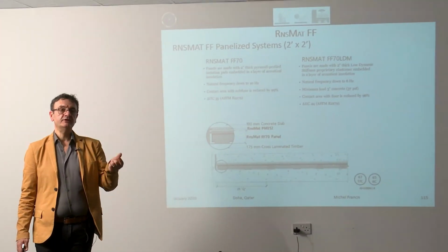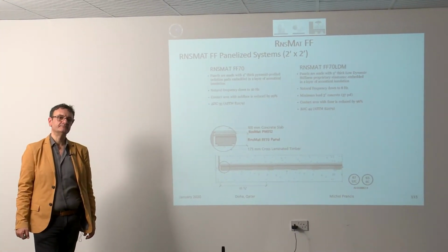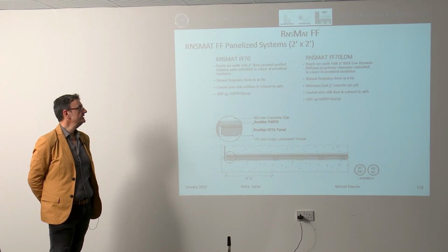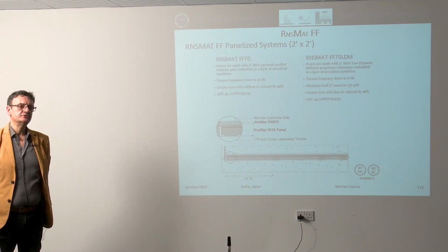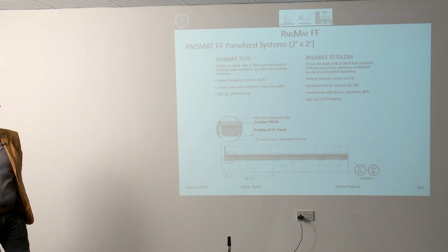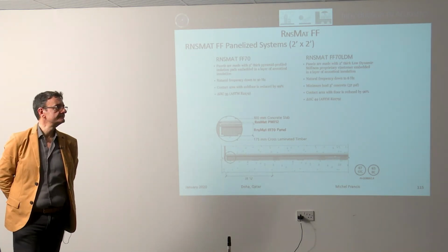So you can say if my IIC is 30, you can make it 65, which is written here. The slab without your mat is going to be 30, and if you add the underlayment to the slab, it's going to be 65. That is what it means. The delta IIC is as per ASTM E2179, so there is a special procedure to measure it. But again, I must caution you not to give it as a hard engineering number. It's an estimation number, and it can give you a good estimation.